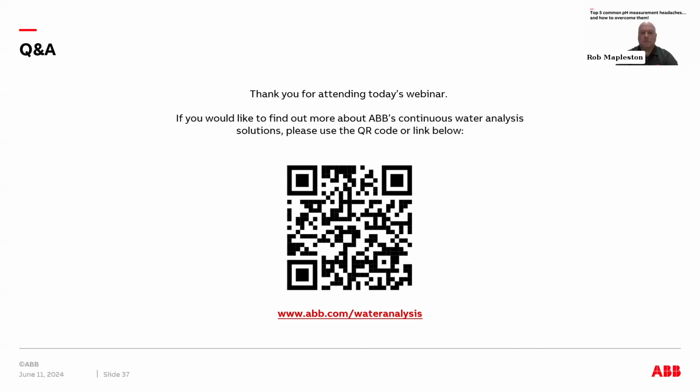But more importantly, it's the reference design. We want a reference electrode that is packed full of KCl salt if it is a sealed design, because I mentioned sealed designs aren't really ideal for high purity. There are versions that have a slurry of KCl salt, which makes it less maintenance prone, but it won't last as long compared to a refillable design with KCl salt being added to it.